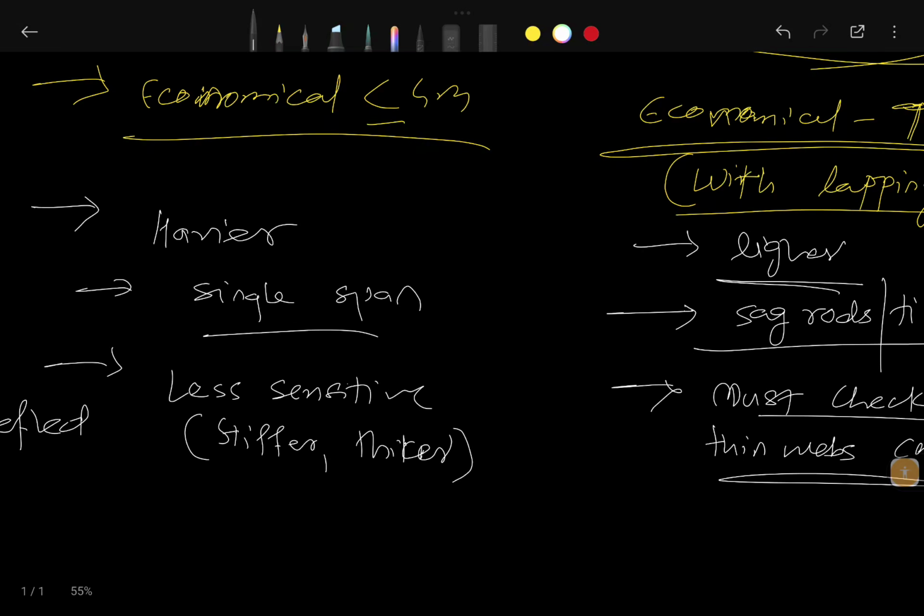And second important point, with respect to bracing: for main structural bracing, stability of frame, use hot form angle bracing. For roof and wall diagonal bracing of sheeting, cold form strap or rod is sufficient.